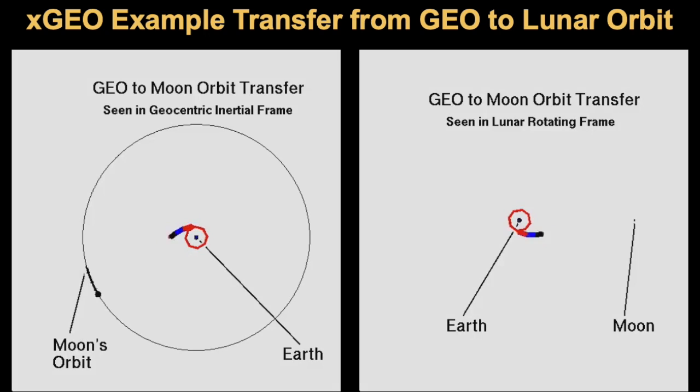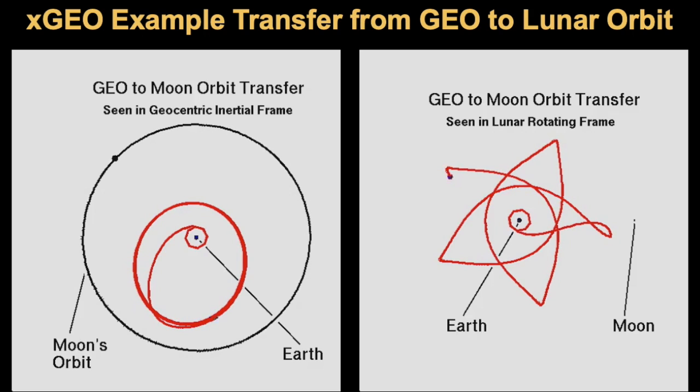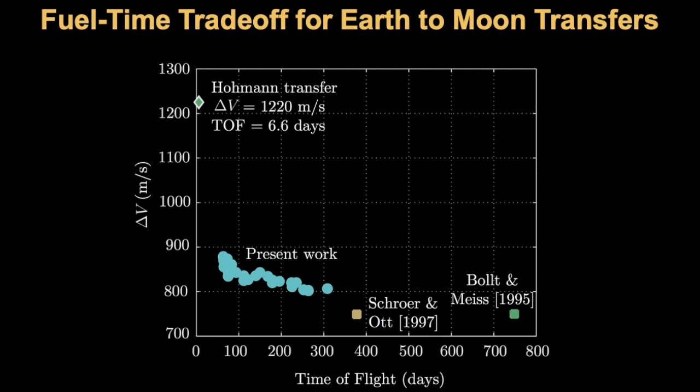So let me show this example again, because this is a trajectory that, after an initial large delta V to leave that geo radius, there were just two other delta V's used. One was used, I think around here, where we had a close approach to L1, and then a final one just to get onto a stable orbit. And those added up to less than 100 meters per second, after having left geo. So this used the connection between resonances and these ballistic captures. Hopefully this gives you an idea of the type of phenomena that are possible.